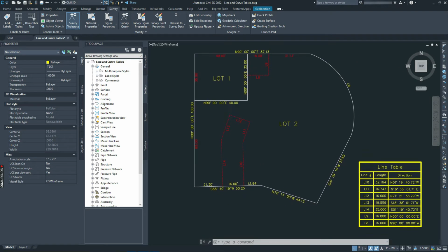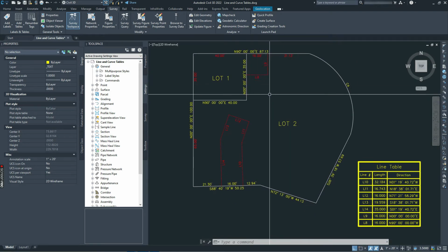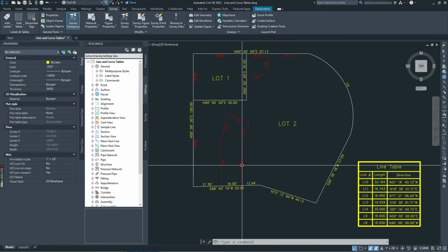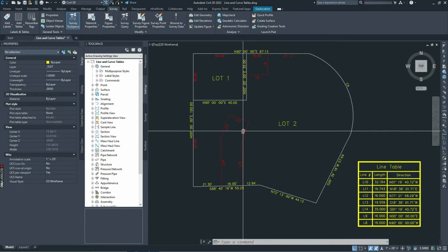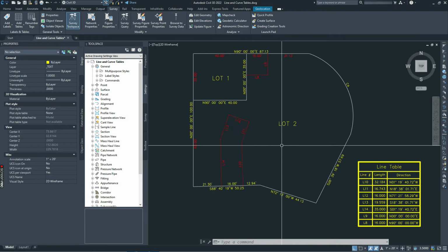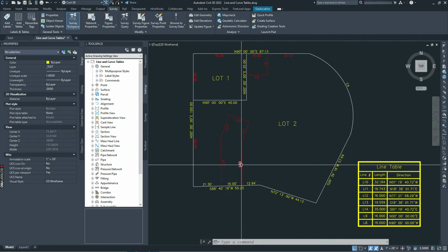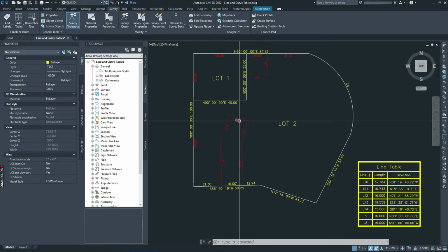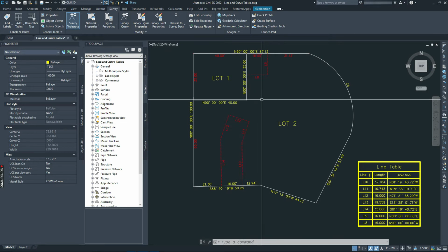The other thing that I want to make sure that I do is in my drawing, I want the line table tags to be numbered in some sort of a logical way. So if this is L10, I don't want this to be L23, and this to be L6, and this to be L19. If somebody's looking at this once I've printed it to a piece of paper, and they see L10, but they're looking for L12, I want them to be able to follow this line around and say, oh, there it is. We want things to kind of progress in a logical way. But the other thing that we want is for our numbers to start from 1 in this example. That would be handy.